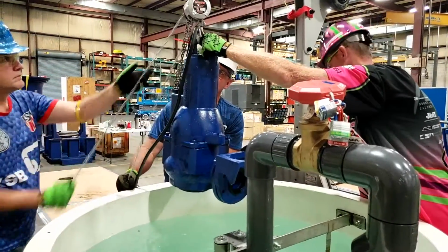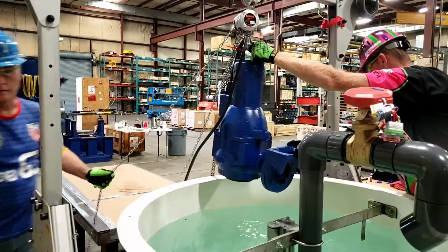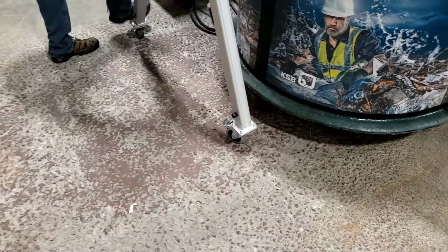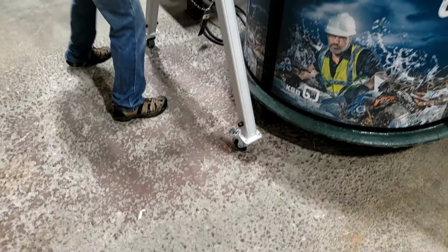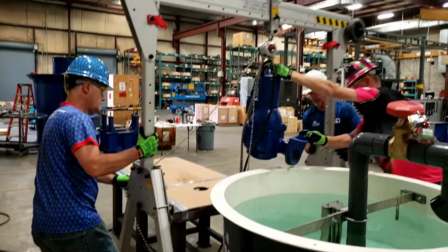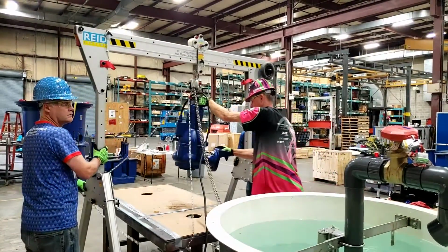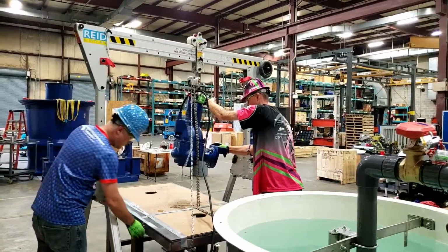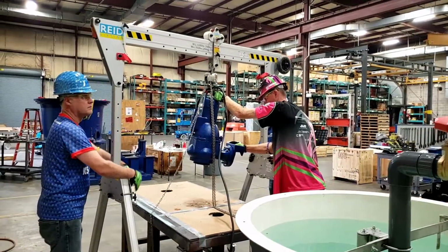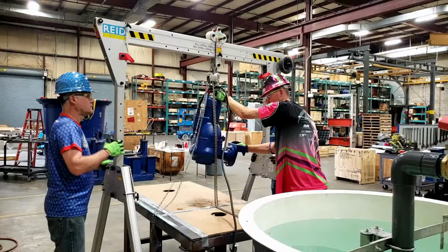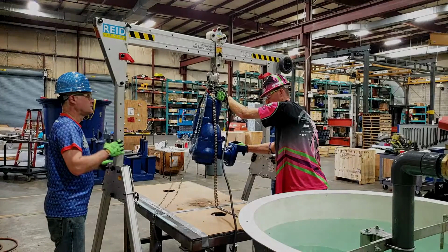Once the pump is raised to the desired level, you may unlock the gantry wheels. Note, the gantry wheels must be locked while the pump is being raised at all times. Once you have unlocked the wheels, you may now move the gantry with the pump attached to the pump service table. You must use a minimum of 3 people. One person must be in contact with each end of the gantry, and another person must be holding the pump to eliminate excessive swinging of the pump.